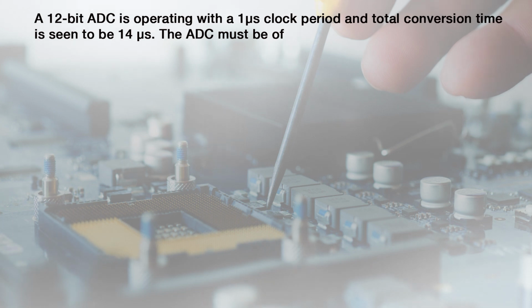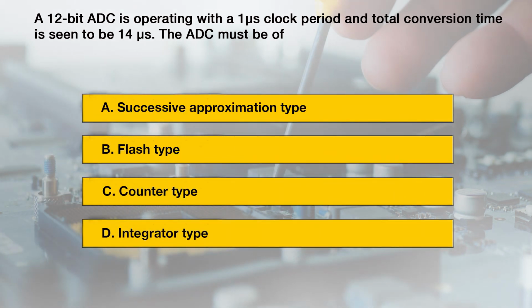Now, the next question is, a 12-bit ADC is operating with a 1 microsecond clock pulse period and total conversion time is seen to be 14 microsecond. The ADC must be, so here we have number of bits given which is 12 and total conversion time which is given is 14 microsecond. Here we have 4 kinds of ADCs: successive approximation, flash type, counter type and integrator type. So, integrator type, dual slope integrator and single slope integrator type ADCs, they require 2 into 2 to the power n plus 1 in the worst case.